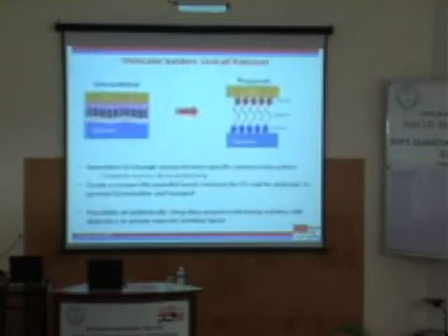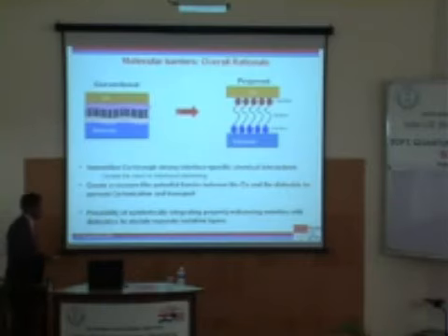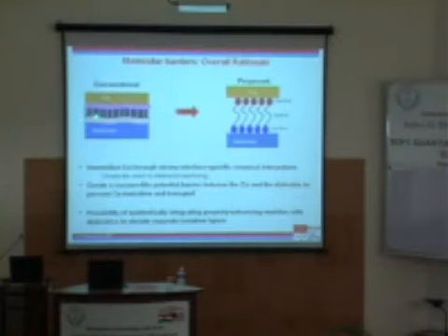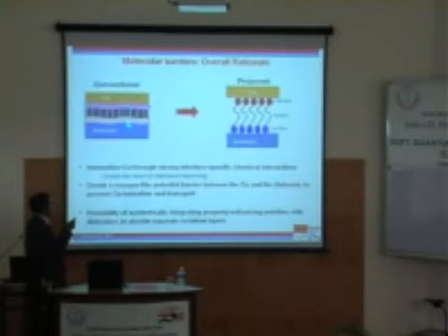So we tried a completely wild idea. This was an undergraduate project actually of 5 years ago, and the amazing thing is it worked. And of course we have been exploring various aspects of this for the last several years. The idea is, instead of taking a brute force approach, which works quite well for micro scale but doesn't work well for nano scale, here you put tantalum or tantalum nitride or some other material where the interaction is minimized to some smaller length scale, and these two stay separate and everything is fine. But as I said, you need a critical thickness of this for this to work.